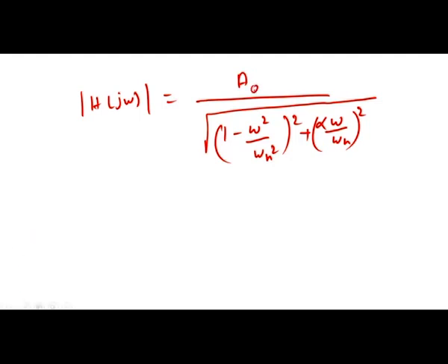Now if you expand this and substitute alpha equal to 1.414, this damping factor represents the damping factor of the Butterworth filter. We have discussed in the previous lecture that all the audio filters are Butterworth filters, since the response of the Butterworth filter for this damping ratio is flat in the pass band.